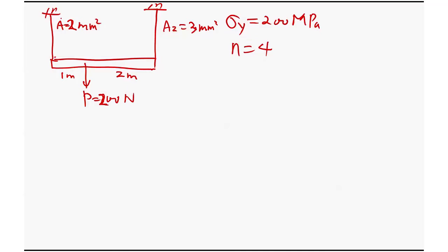Because we know from here, immediately you find out the sigma allowed, right? That equals sigma y divided by 4, and you know, so it's 50. So basically, we want to find out the stress. Are they below 50? Then we're safe. Are they above 50? Then we're not safe, right? So that's the goal. Okay, now next, how can you find the stress here and the stress here?